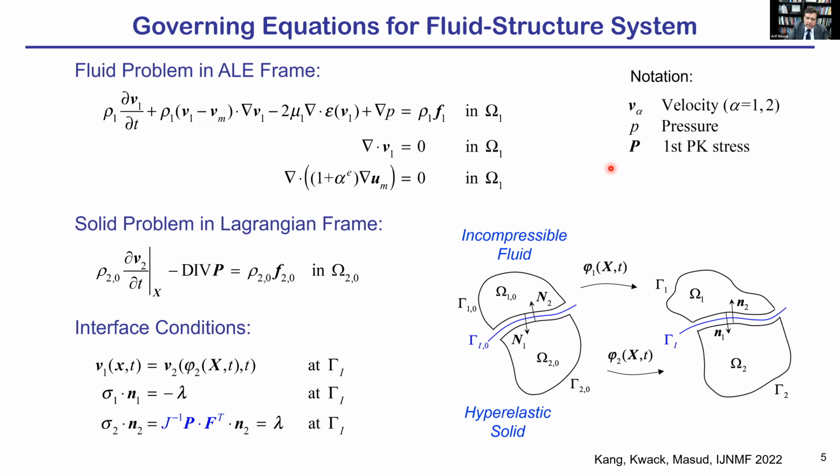So let's look at the governing equations for the fluid-structure system. We write the fluid equations in the current frame, in an ALE frame, arbitrary Lagrangian-Eulerian, to be able to account for large deformation of the interfaces. The continuity equation, the boundary conditions, and the equation for being able to move the mesh. So this is mesh motion.